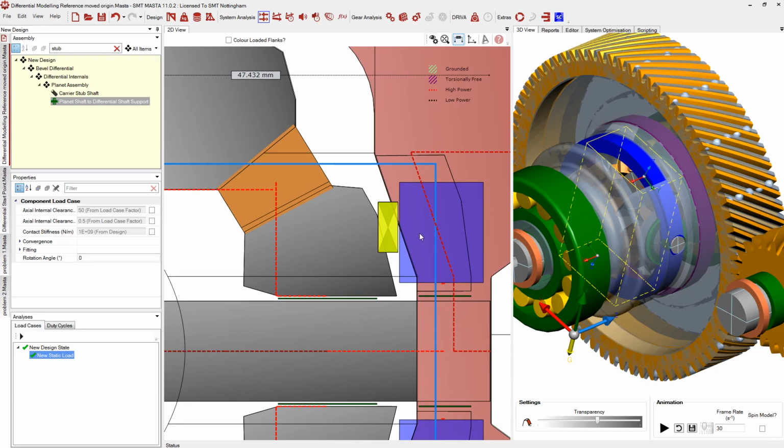If it was modelled in the other orientation, it would be a radial clearance bearing. That allows us to model the connection between this component on the left and the stub shaft component over on the right. So we can get an accurate representation of clearance between those components, and if it moves enough to transfer load, we'll capture that information.